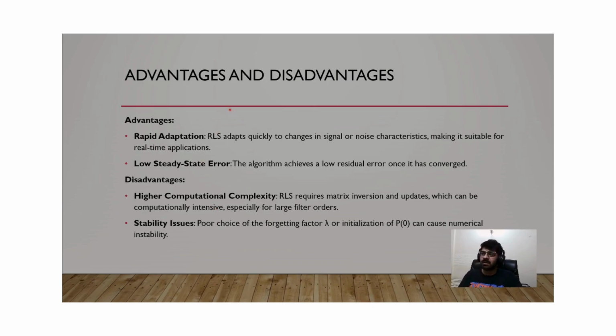Then there are some advantages and disadvantages of the RLS technique. One advantage is rapid adaptation. RLS adapts quickly to changes in signal or noise characteristics, making it suitable for real-time applications. Low steady-state error. The algorithm achieves a low residual error once it has converged. Then we have some disadvantages.